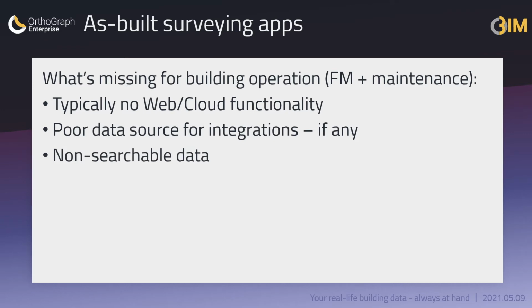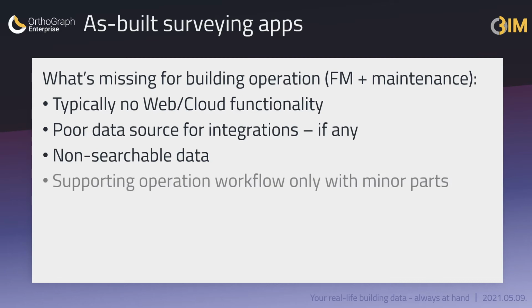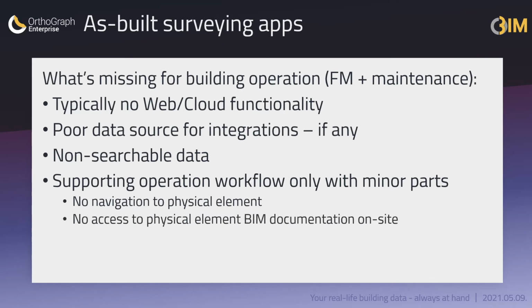Just think about how important it is to find an element in the operational BIM based on its unique identifier, for example its RFID. That's the key to digitized operational workflows. Communicating by using simple links to elements would be required for the maintenance people to navigate to the subject of repair. This would save time for the maintenance person, but more importantly, it would shorten downtime. Being able to bring up any element by its RFID on site with all details would help the maintenance people in their work, reduce repair times and provide increased quality of service.